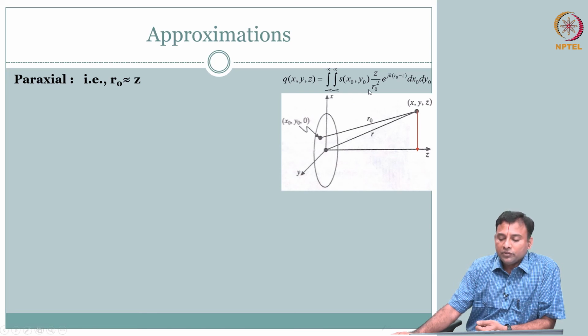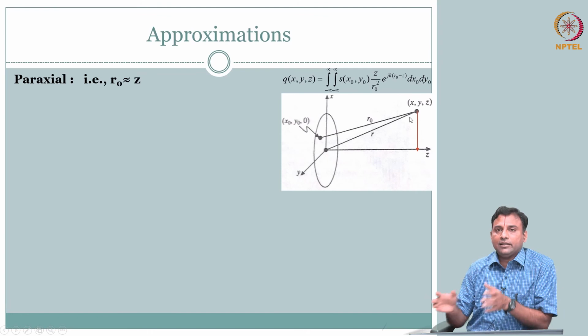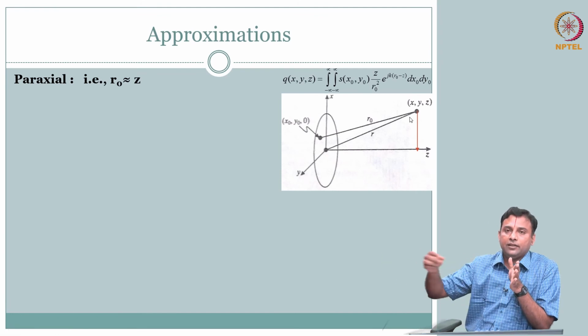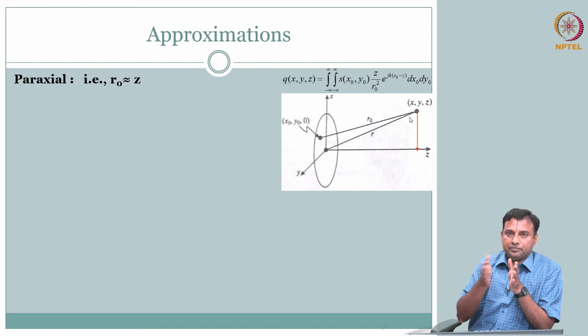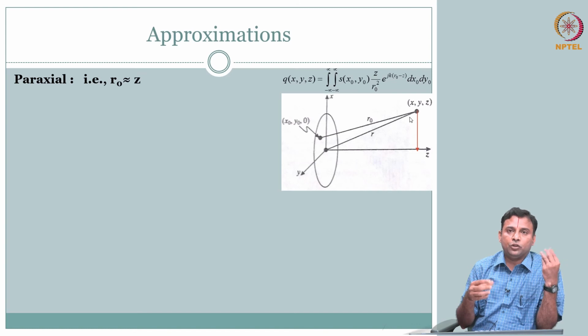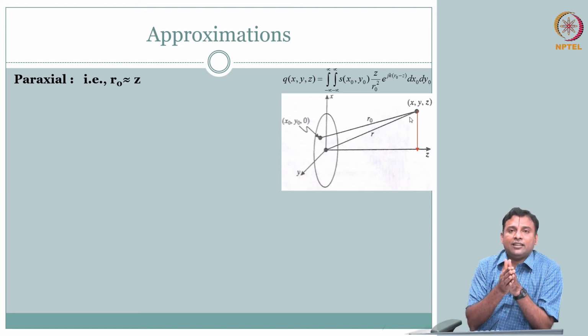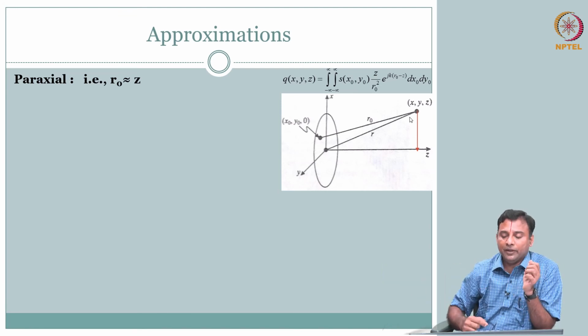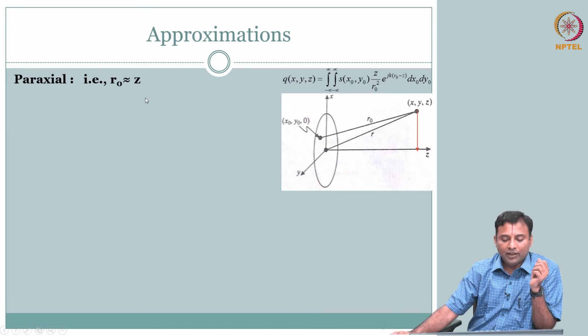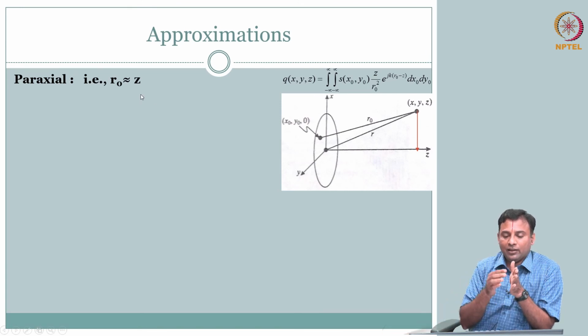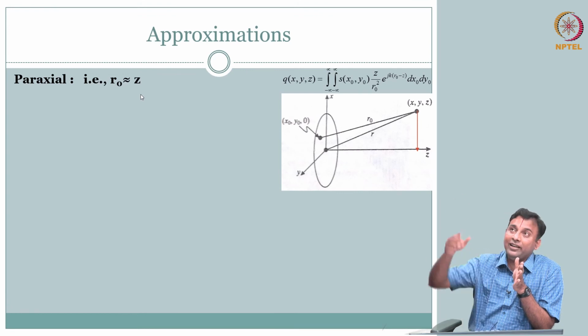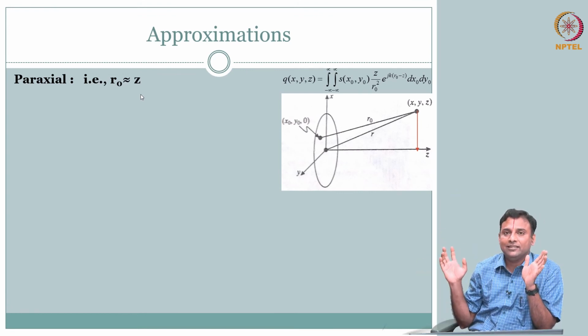What we are going to do first is that we are always interested in something at the center of the transducer, because in the end everything falling on the surface is going to get captured. So if I have to register that, I will have to register that at x naught comma y naught comma 0, for example. That is where the transducer was located when you got this time trace of the signal, which is depth. So in some sense we are interested in the pressures that are close to the z axis. I am not really interested in something that is far off the axis.